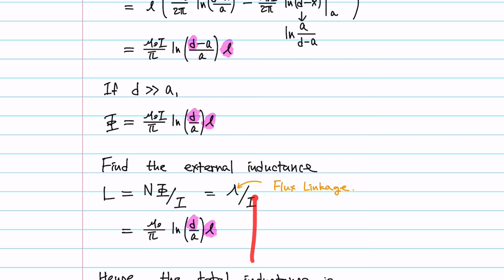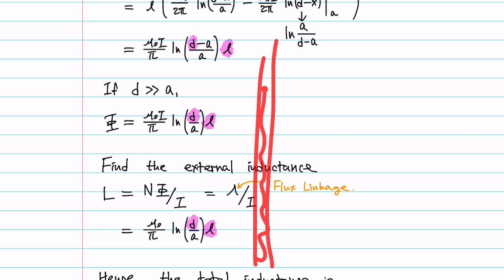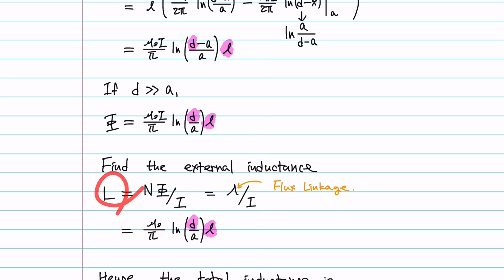Instead, you create a trace right next to each other so that the surface area between the two is minimized. That is one way you can reduce the parasitic inductance that you don't want in your system.